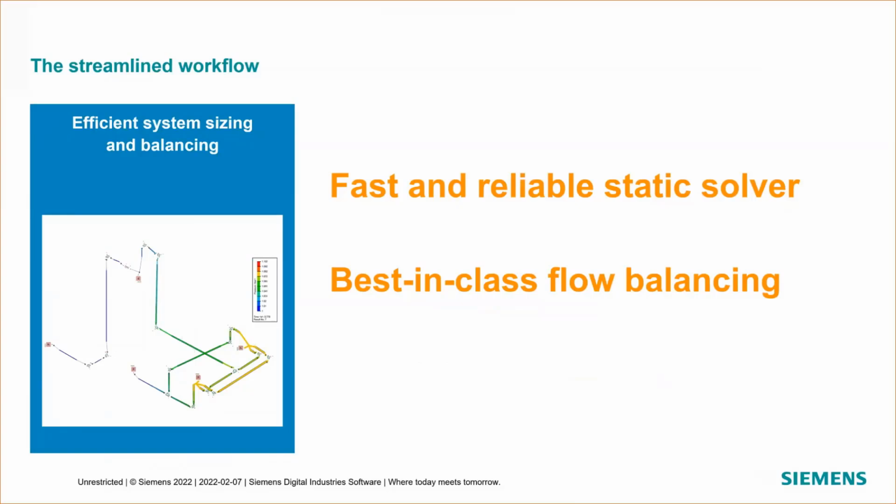SimCenter Flowmaster for Solid Edge, as supplied, comes with a best-in-class flow balancing capability to perform this type of simulation. This isn't done by running an optimization, so you don't have to run many simulations. Basically, what you do is enter into the datasheet the flow that you want through a particular orifice or valve, and it will return directly what the size of the orifice plate should be or what the valve position should be, without having to do a parametric run that may take a bit of time.